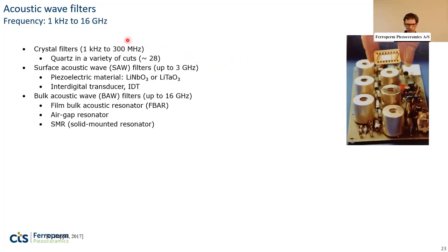In these cases, the manufacturers tend to use single crystals. More traditionally, it's been made of quartz in special cuts, meaning special directions compared to the crystallographic axis. And the frequencies may be even down to 1 kilohertz and as high as 300 megahertz.